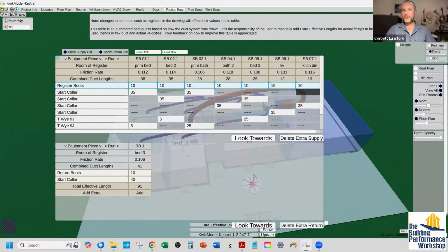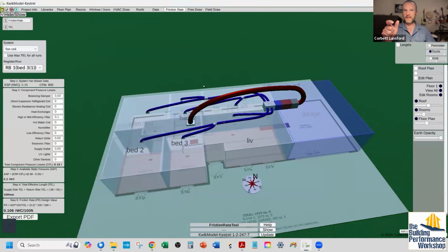You could also start choosing different fittings at this point, right? Yes. Like they make things that have vanes in them. They're more expensive, exactly, more turning pieces, things like that. Usually the problem is going to be, especially if you use the trunk and branch style of duct layout where you have this long extended plenum trunk and way out the end you've got stuff coming off it, those typically are going to have the friction rate be too low.